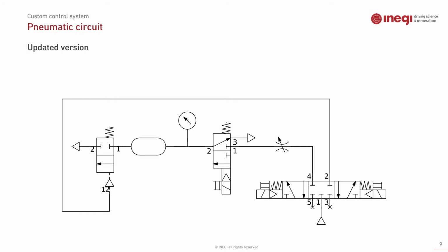We added a new digital pressure gauge with LCD and voltage output for a controller, one 3-2 valve to control feeding, and one 5-3 valve with closed center to control the pressurization and trigger the 2-2 valve for firing. This allows us to simplify the pneumatic circuit by using a smaller number of components, taking less space but also reducing air leaks. Additionally, it also allowed us to replace some valves that were closer to end of life.